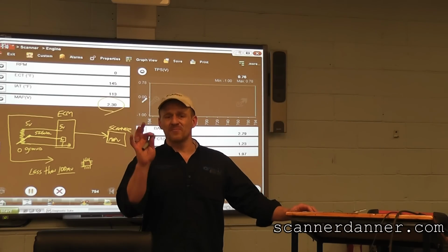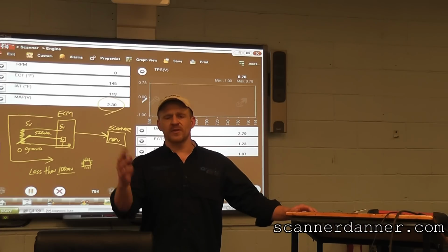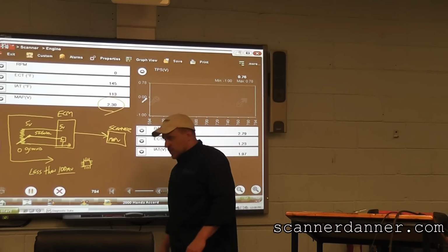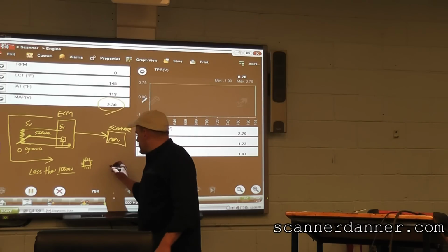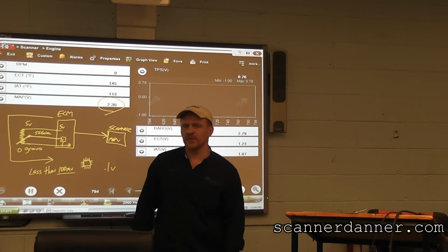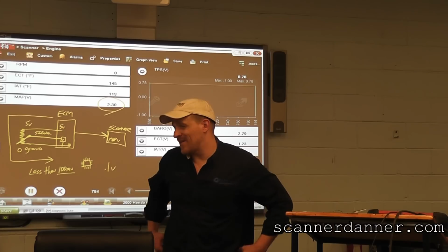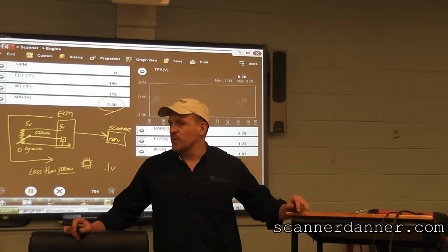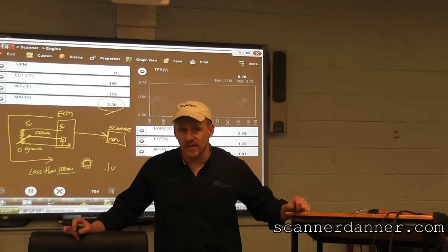There will be some remaining on that ground circuit with a tolerance of 100 millivolts. So 1/10 of a volt or less, that would be 0.1 of a volt or less, is acceptable ground voltage on a sensor circuit. Most of the time on a good one, Tom, you'll see 20 millivolts. 0.02 would be a typical ground reading on a sensor.